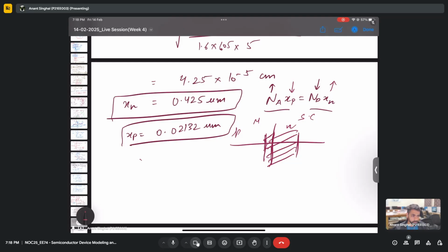I mean, we also use this concept to reverse bias this PN diode when we form a FET. Transistor, MOSFET you are saying. MOSFET, yes. We also do the halo implants, increase the doping for the substrate.